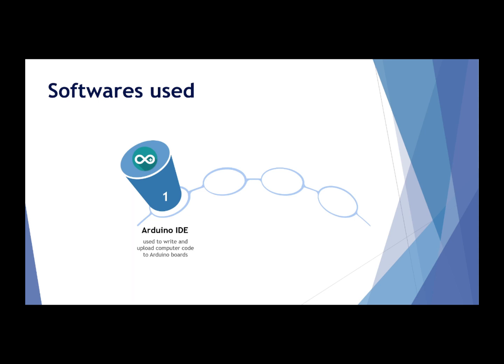Using this we programmed our Arduino in C++, and along with it we also used Proteus. The simulation that you have seen is in Proteus 8 professional software, where you simulate the circuit before final assembly, to check whether any difficulty occurs.